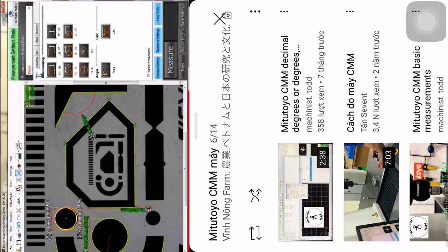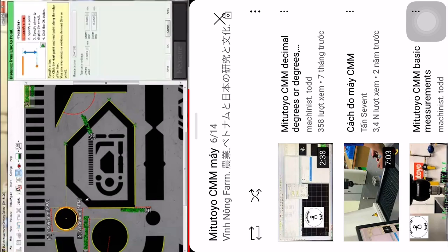Now we're ready to measure. Go back to Basics, Line to Point, select the datum line, select the first point, and place the value. Input the design value, as well as the upper and the lower spec limits. We're going to select Next, select the datum line again, the next intersection point, and place the value. All we have to do is change the design value. We don't have to put the tolerances in again as long as the tolerances stay the same. Select Next, click the next datum line, the point, place, enter in the new design value.